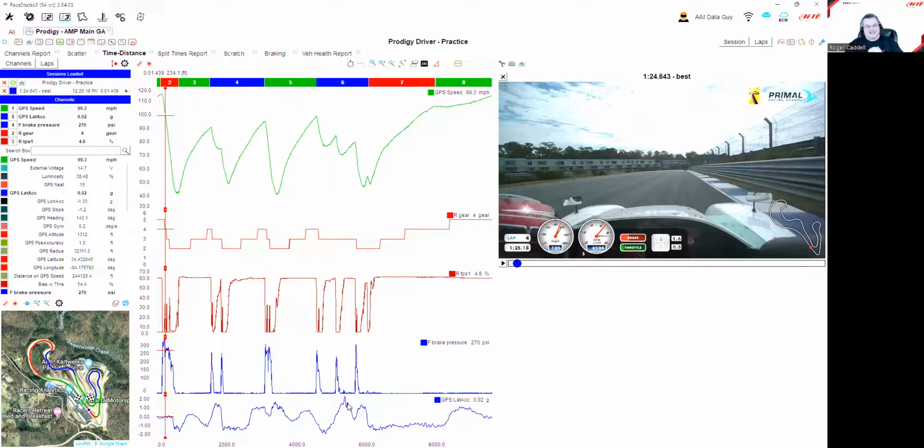What we really like to see, kind of a home page for the driver, is whatever the driver inputs are. So you are doing things with your feet, and you're doing things with your hands, right? And in a perfect world, we would have that bit of information because that's how you're manipulating the car. In this particular data file, the steering sensor seems to be broken. So the next best thing, and we always have to go to the next best thing. It's motorsports in general, right? You never give up. So okay, the steering didn't work. What's the next best thing to tell us what you did with the steering wheel?